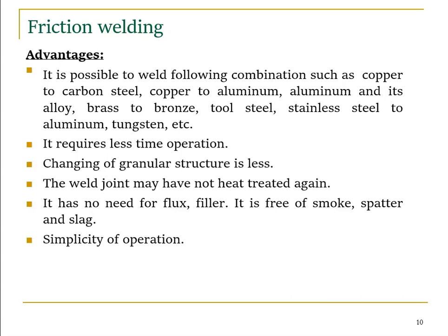So it requires less operation time. Change of granular structure is less because the heat is generated at the end or at the edge of the workpieces. So it won't affect the other part of the workpiece. So only the edge gets heated. So the granular structure change, if you see, it's very less.